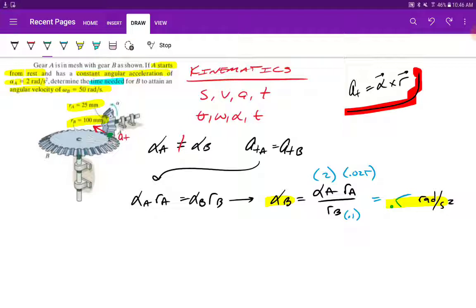So we know if wheel A has a constant angular acceleration, it's going to be A and alpha because they're related, right? Well, think about it. We know that the tangential acceleration for the point of contact between A and B is going to be the same. And if the acceleration for A is constant, that means that the acceleration of B is constant. So for B, we also have a constant A and alpha. So B having a constant A and alpha is very important. So I'm going to just kind of underline that. Why? That's because I can now use the constant acceleration equations.